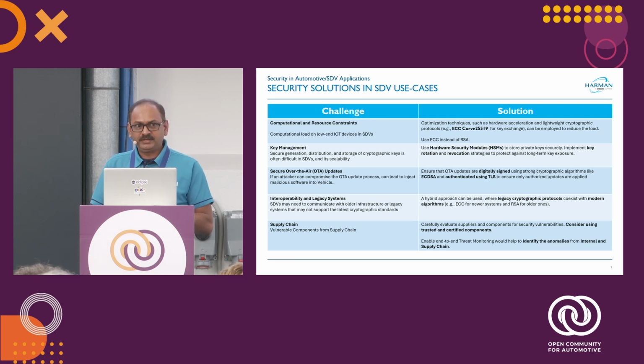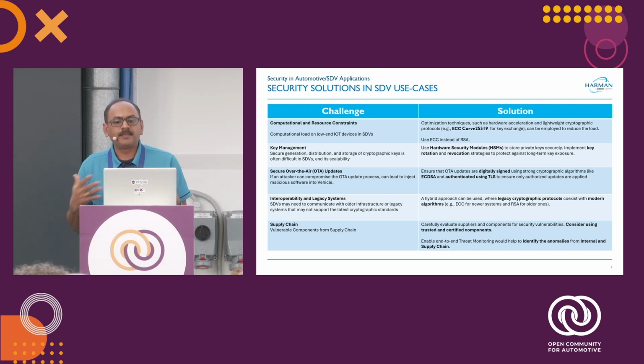And key management: especially on the cloud, there are lots of solutions already available to manage the keys. But in the vehicle, if you want to manage the keys, how we generate the keys, how we actually rotate the keys, and how we distribute the keys to different applications in the vehicle, key management is very, very critical. And that's where we would like to have some kind of HSM-enabled libraries or platform components, so that they can help all the applications to generate the keys, as well as handle rotation and other requirements in the key distribution area.